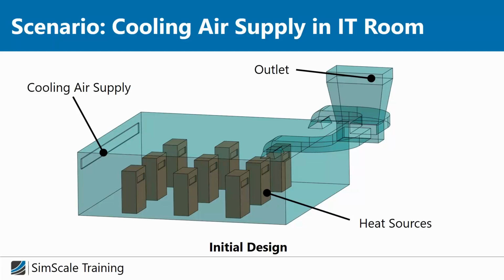For example, if you want to run simulation on your own, sometimes you need this kind of IT room because you need so many servers to run the calculations. And when you think about such big IT rooms, you should keep in mind that cooling is essential. In most cases, I have around 10 servers in such a rack. And if every server is consuming around 1 kilowatt of power, I have in total up to 100 kilowatts of energy.